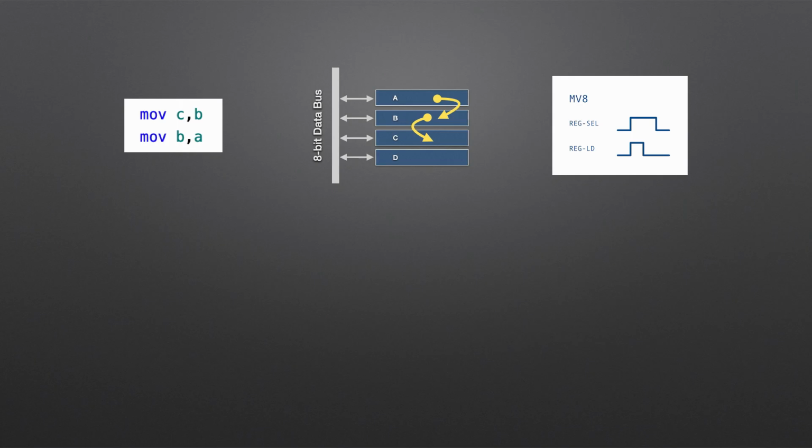Effectively, that would just cause the register to store the 0 value now present on the data bus rather than the intended value. The timing chart therefore leaves a nice gap to let the value stabilise on the bus and then leave it hanging around well beyond the point the load line is dropped. So the computer knows what to do, when to do it, and relatively speaking, how long to do it for. Easy, yeah? No. So where does the computer get these pulses from, and what makes the top one last twice as long as the bottom one?